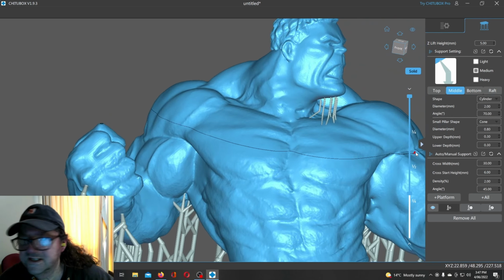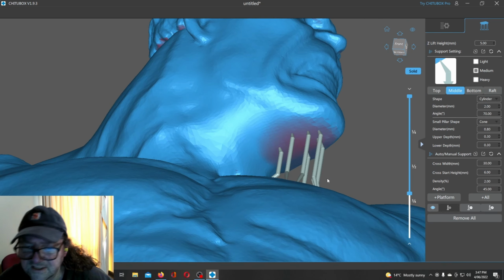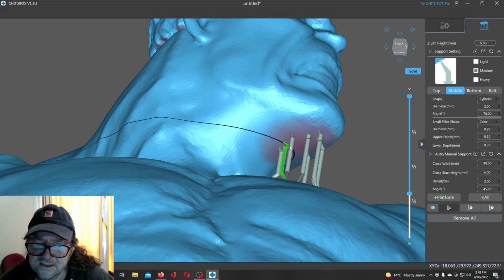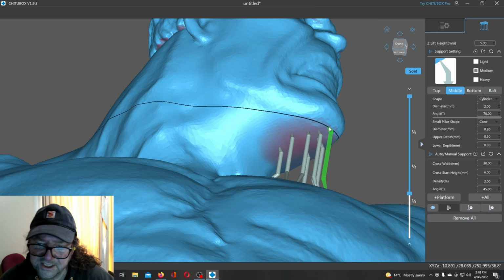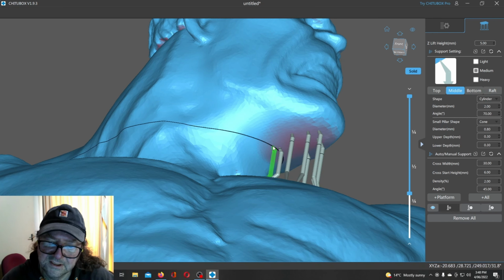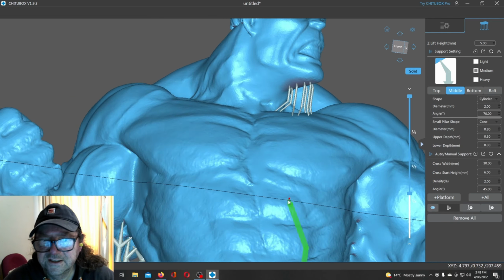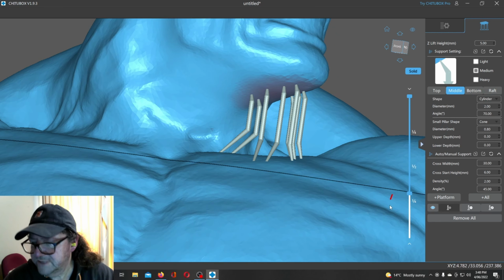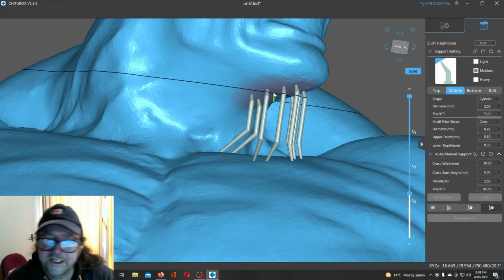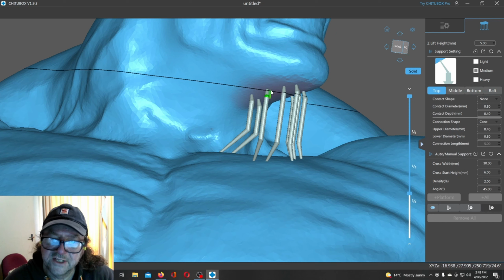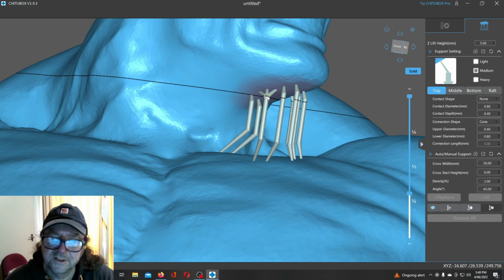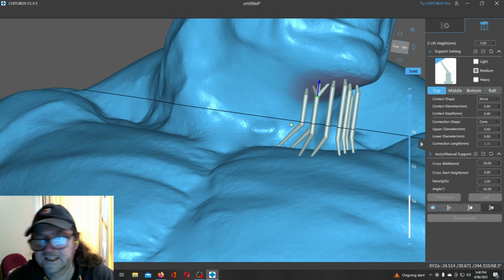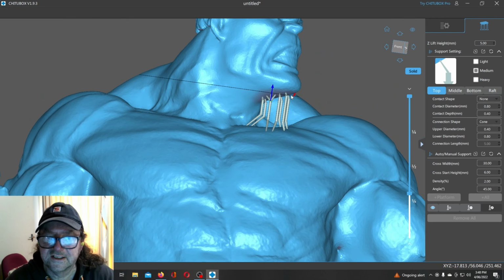So they're easy to knock off, but that's an island in itself. So let's just see how it starts. Oh, it's not an actual island, it's just a very sharp angle. That's okay. And they can also be done with fan supports. That's where you go modify, double click on the area to duplicate and do that. Escape, shift the ball down. Like that. So there's your fan support instantly.